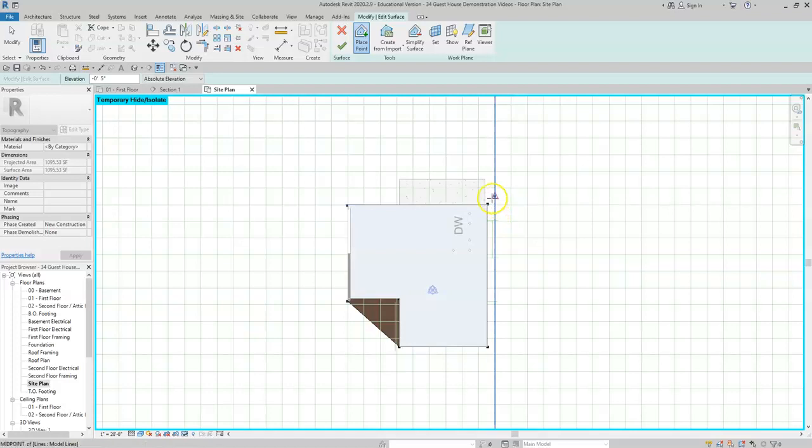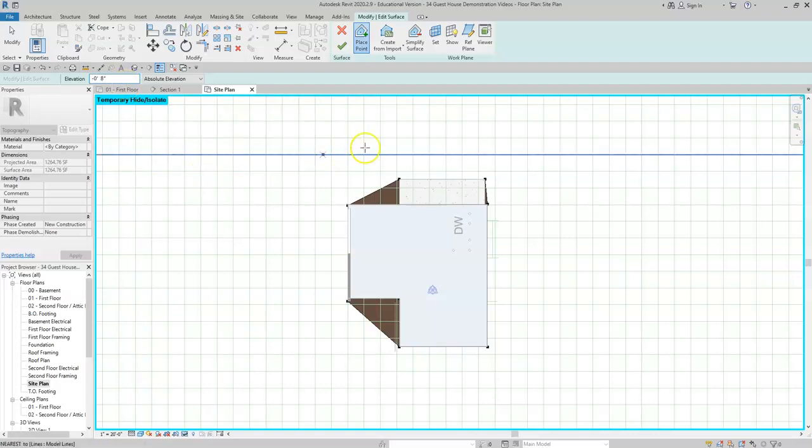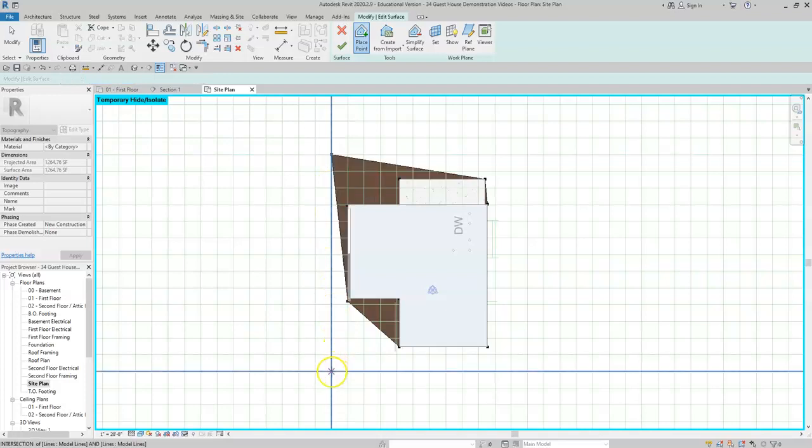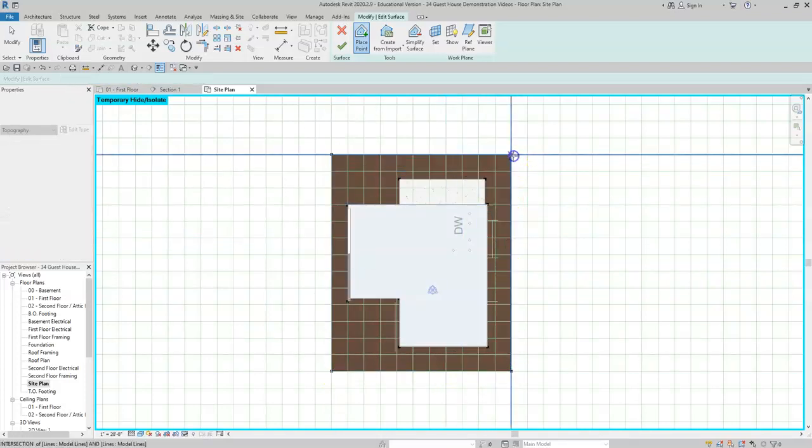Your porch should be here, and you may not see this very well. So that's 0.5, and then now every point beyond these corner pieces needs to be lower than 0.5. We can go ahead and go down a few inches more, or we can leave it just 1 inch below this, but it needs to be less than 5. I'm going to go ahead and go, let's say, -8 inches. All right. We won't see much of a contour here, but I'm going to go ahead and just give it a boundary, just a few grid marks away from where we were.